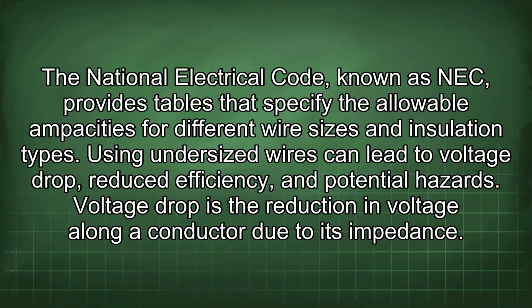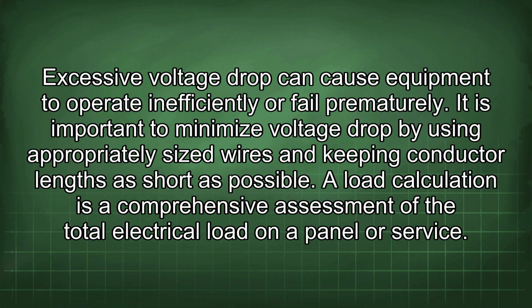Voltage drop is the reduction in voltage along a conductor due to its impedance. Excessive voltage drop can cause equipment to operate inefficiently or fail prematurely. It is important to minimize voltage drop by using appropriately sized wires and keeping conductor lengths as short as possible.